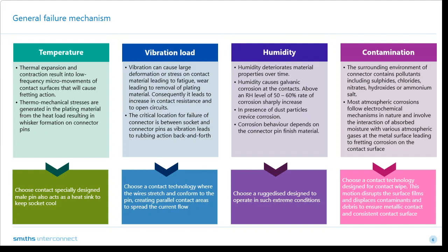And finally, contamination. The surrounding environment, if it's an industrial environment that is polluted or contains pollutants like sulfides, chlorides, nitrites, hydroxides, or ammonium salt, it just creates a failure mechanism to set in.